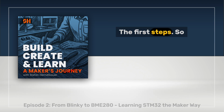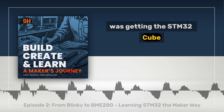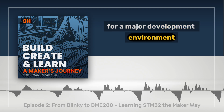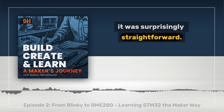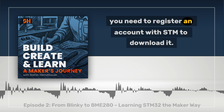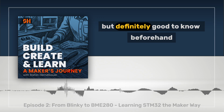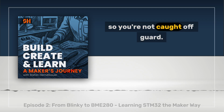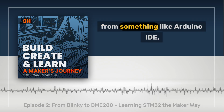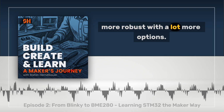The first steps. So the very first thing on this embedded journey was getting the STM32CubeIDE installed on my Mac. And honestly, for a major development environment, it was surprisingly straightforward. A quick heads up for everyone else diving in though, you need to register an account with ST to download it. It's a small, quick step, but definitely good to know beforehand so you're not caught off guard. Once you're in, you immediately notice the difference from something like Arduino IDE. It feels more professional, more robust, with a lot more options.